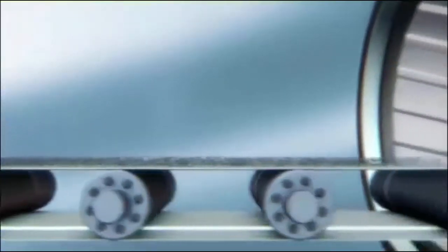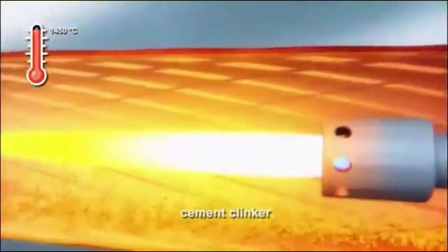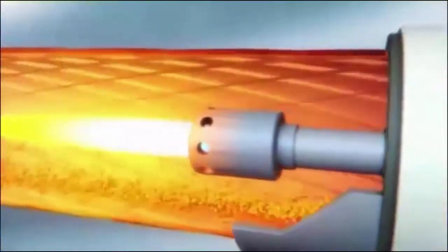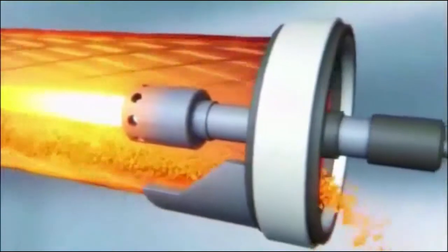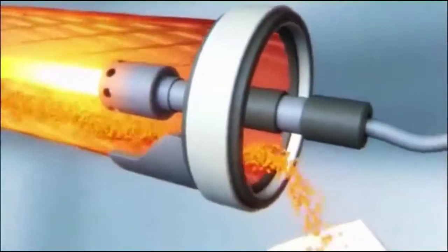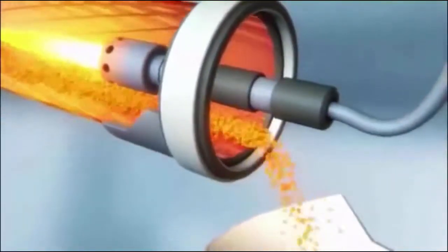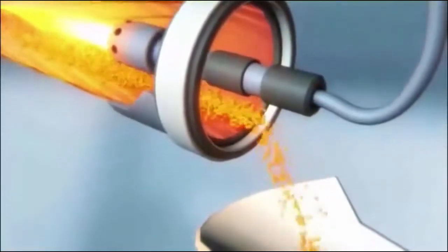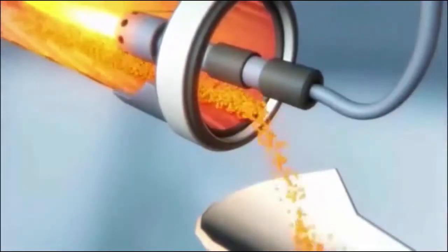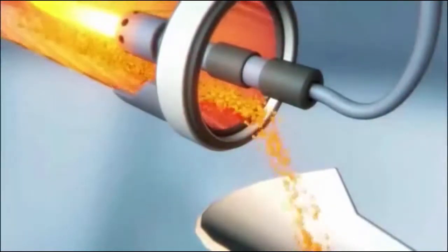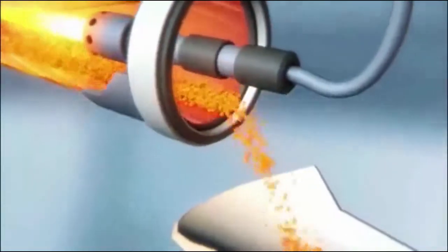This raw mix is then transferred to a rotary kiln and fired at temperatures of about 1450 degrees Celsius to produce round-like particles measuring about 3 centimeters, known as cement clinker. Sintering is the name used by experts to describe this important process, which needs an enormous amount of energy. In this incineration process, chemical compounds are formed which later cause the cement to harden when mixed with water.